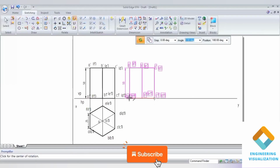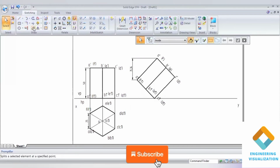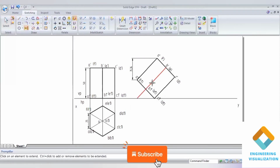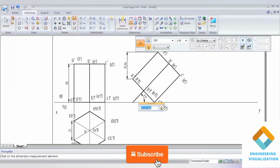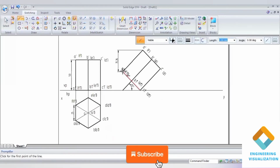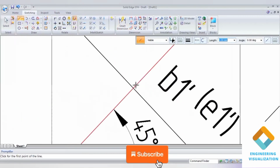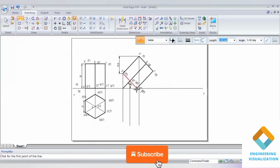The inclination is 45 degrees. So incline 45. So it has been inclined. Okay, now extend the axis, find out the angle, and project downward to complete the second position, top view. So draw the projection lines downward here to complete the second position, top view.